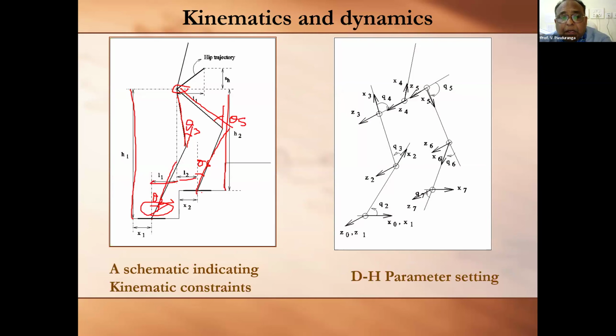This is theta 1 here, and theta 7 here, and theta 4. Once again, this is theta 4. So these 3 things we have to derive. We already planned to derive theta 2, theta 3, theta 5, theta 6 by using the geometry or inverse kinematics. And if you see this theta 7, it is resting on the ground, so theta 7 is assumed to be 0. So we are left with 2 unknowns, theta 1 and theta 4, to be derived.